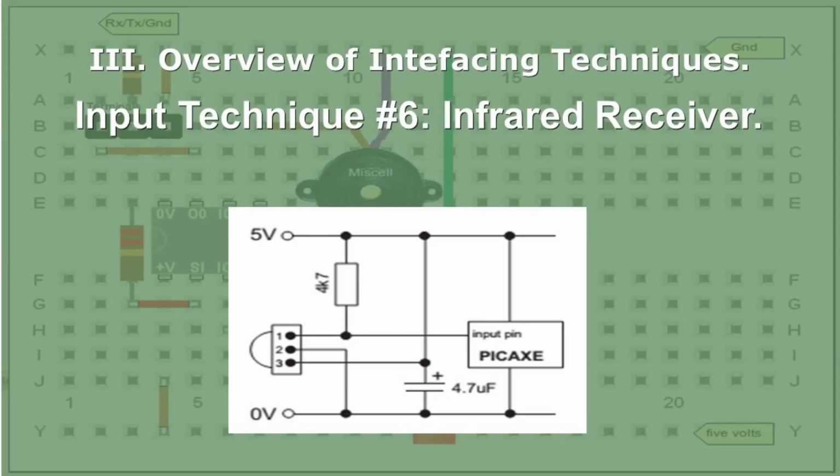This is an infrared receiver that actually has a clock out of it, depending on what it gets. I've never played with one of these, but an infrared receiver can interface into a microcontroller. Depending on what kind of microcontroller it is, if it's only 3 volt inputs, you'd have to do some translation. And depending on the infrared receiver, it has a 5 volt output or 3.3 volt output. There's a lot of stuff now that's 1.8 volts and some of the higher end stuff.